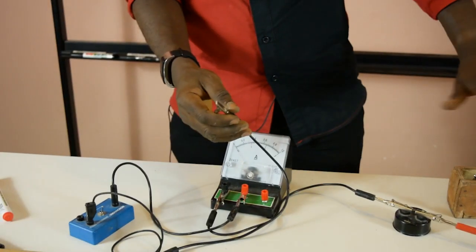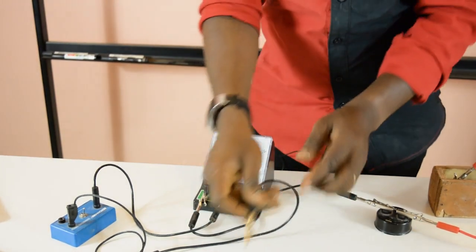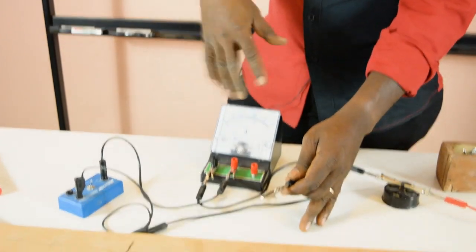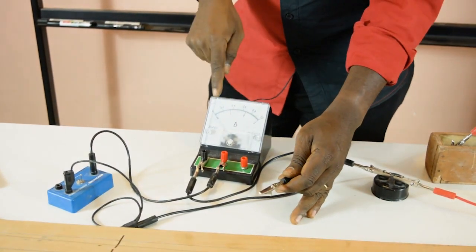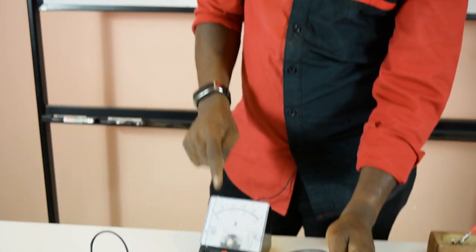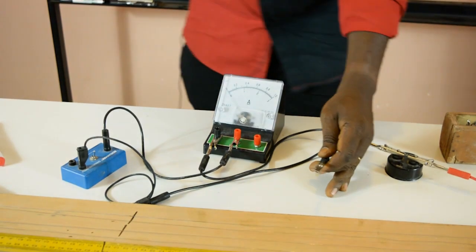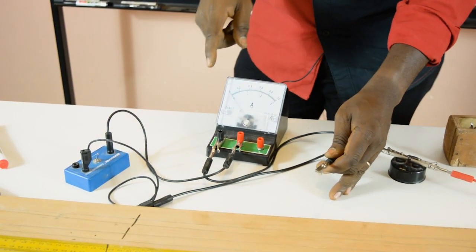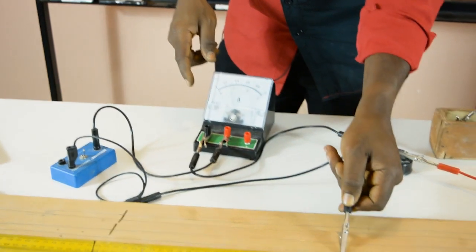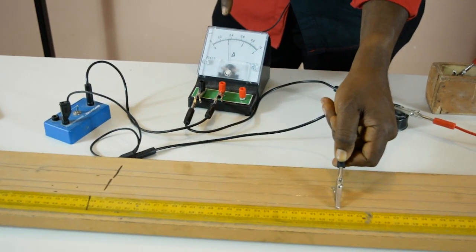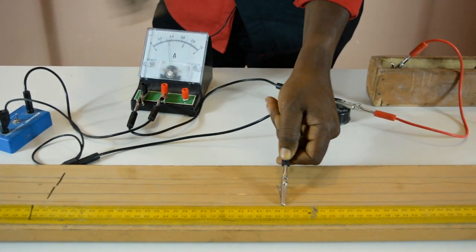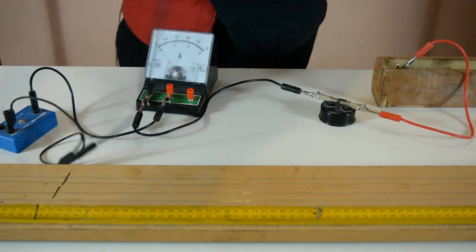I have connected the circuit properly and in the proper sense. That's why I'm reading it there. If I did not connect it in the proper order, the pointer here, this ammeter, will not go clockwise. It was going to go anti-clockwise, telling you that you have not connected it in the proper direction. So now this is telling me that my current is reading somehow here. That is, the circuit is now operating. So the experiment proper now starts.